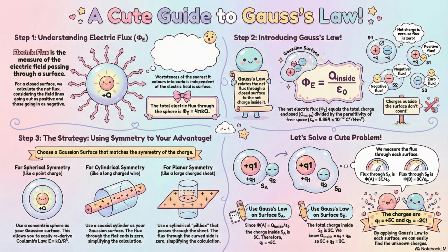It is. If they fail from overvoltage or a high current surge, they are notorious for failing in a pyrotechnic fashion. They literally explode, they spew flame and smoke. It is not a gentle failure. So how do designers even use them safely? Aggressive derating. The safety guidelines recommend derating them by 50% or even more of their rated voltage, just to give them a massive safety margin. That's a phenomenal example of material science just completely overriding the physics. The math says the voltage is fine, but the chemistry says you can only use half of it.